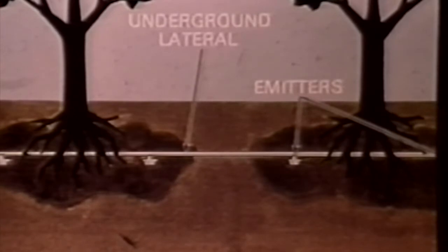The drip system slowly applies water to the soil surface as small or continuous drops through emitters. Emitters can be single outlet, multiple outlet, or line source type. During irrigation, the emitter drips or oozes water at a constant, low discharge rate, normally a few liters per hour. The type and arrangement of the emitters depend on the crop being irrigated. The subsurface system is identical to the drip system in all but one respect. The laterals and line source emitters are located below the soil surface.